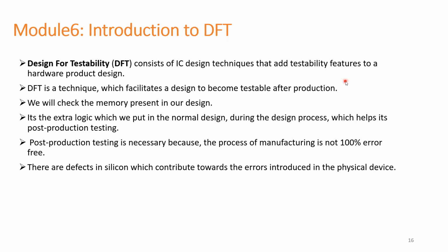The RTL design engineers and DFT team will insert the scan logic as part of the functional code, implemented in the RTL code only. This scan chain will be used for testing post silicon fabrication. That is design for testability. It is used to detect any defects in the silicon while fabricating, as there could be physical damage within the silicon. To detect that, we can use this DFT logic. So this is about DFT.